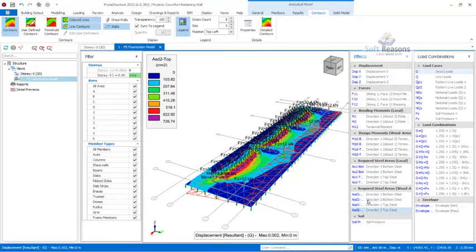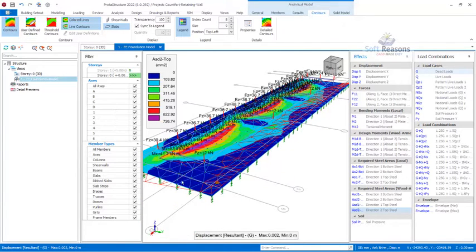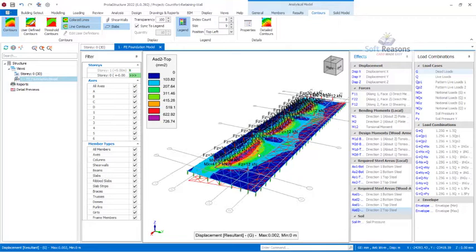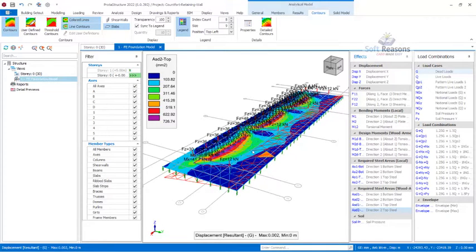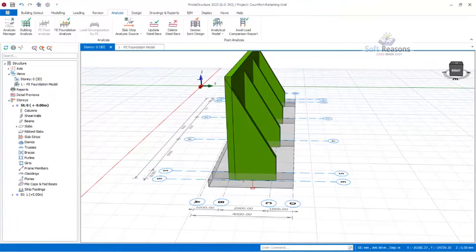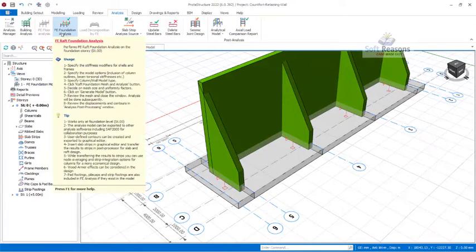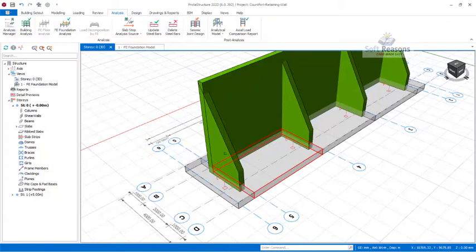So that is it. We are done with applying the effect on the footing on the base successfully. So design is done. We have to now move to generate reinforcement. For us to generate reinforcement, we will have to get back to the physical model. You can leave this analytical tab right there. You may not necessarily need to close it, but if you want to close it, there's no problem. Navigate to the physical model, and since we have done the analysis, you can see over here FA, foundation analysis, checked green, meaning we have done the analysis successfully.